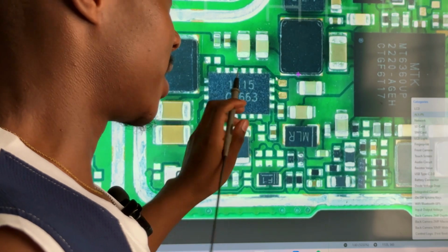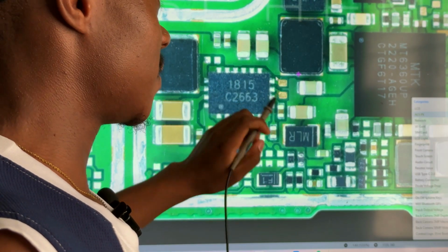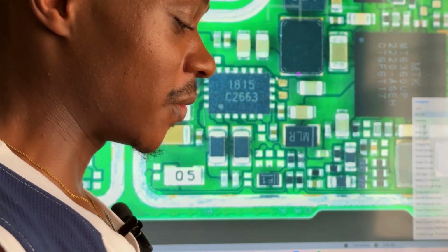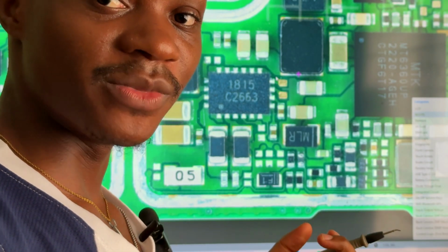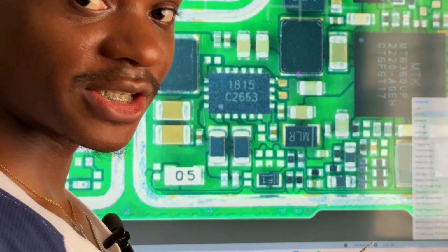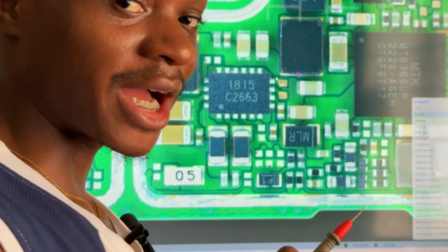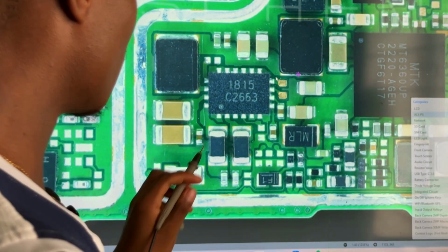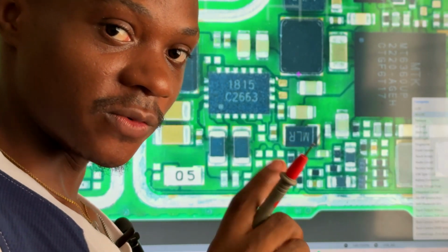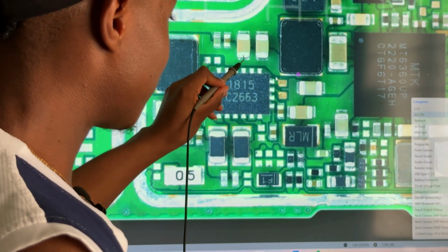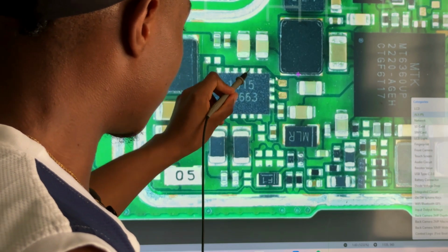So for you to look at the power supply of this sound circuit, you need to understand that sound circuits of mobile phones either use a PMU power supply or a VPH power supply. They don't use a standby power supply like a VBAT. Keep that in mind. So which means that all you have to do, you have to switch on the phone.